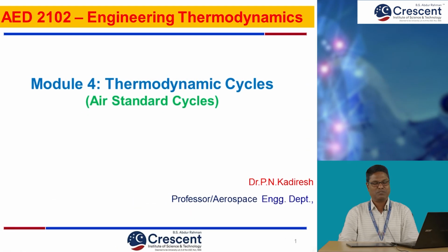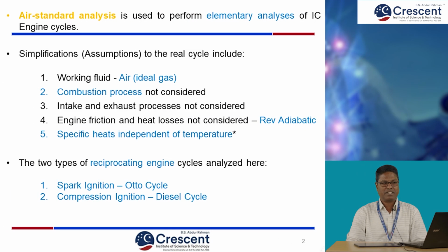Today we will talk about thermodynamic cycles, under that, air standard cycles. Air standard cycle analysis is used to perform elementary analysis of IC engine cycles. In an actual cycle, the medium is air and fuel, or an air-fuel mixture. In air standard cycles, we assume air as the medium.